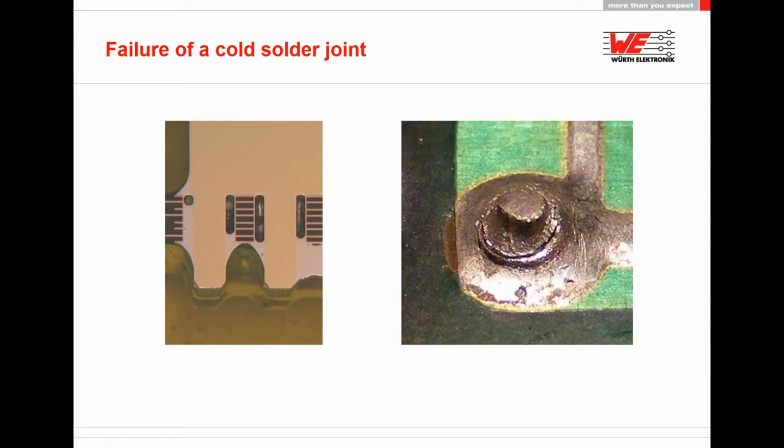Another problem with solder joints is that we can't really look inside the solder joint, and sometimes the solder does not get properly inside. Again, for signals it would work, but for currents, we want to transfer current into the layers. For example, here the current is coming in and wants to go into the layers, but it's not possible because there is no connection.